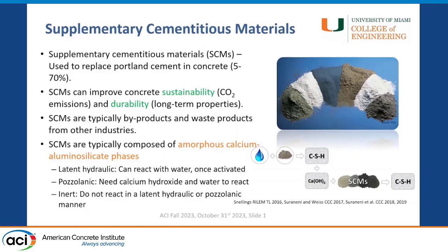So you have your fly ashes, you have your slag, you have silica fume and other materials. And these are typically composed of amorphous calcium aluminosilicate phases, emphasis on amorphous, and these can be classified into latent hydraulic, pozzolanic or inert materials. Latent hydraulic materials react with water once they get activated. Pozzolanic materials require calcium hydroxide and water to react, and inert materials do not react in a pozzolanic or latent hydraulic way, but they have other benefits in your concrete mixture.